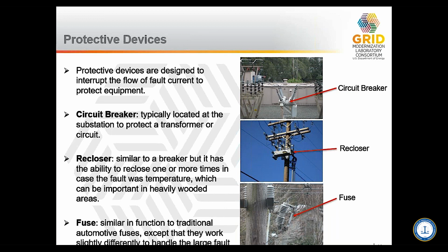Perhaps one of the more interesting devices is called the recloser. It's similar to a breaker, but it has the ability to open and close more than once. And so the key is that we know that some faults are momentary. What I mean by that is there's a difference between an electrical fault when a power line is laying on the ground and when a crow is pecking on an insulator and electrocutes itself. The latter is a momentary fault that's only there for a minute and then clears.